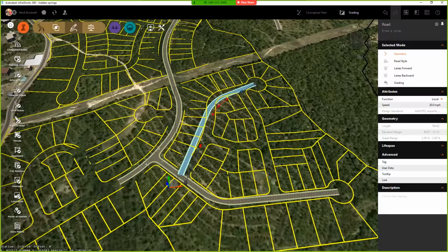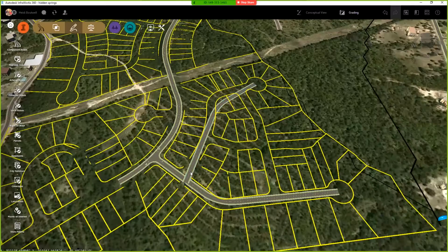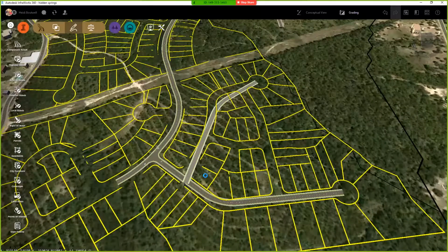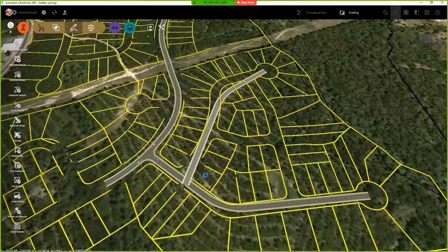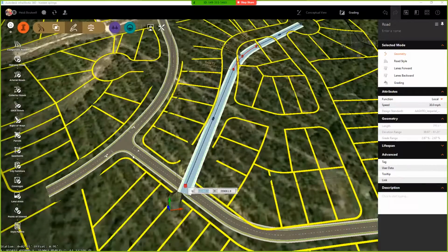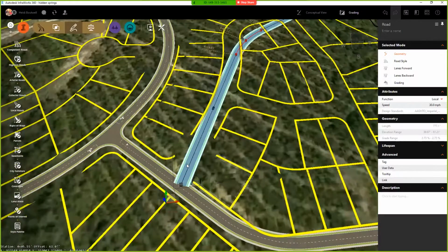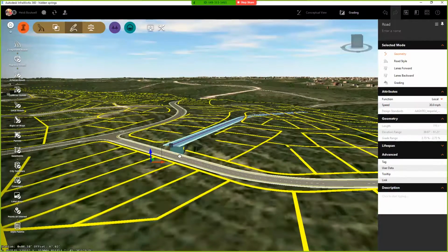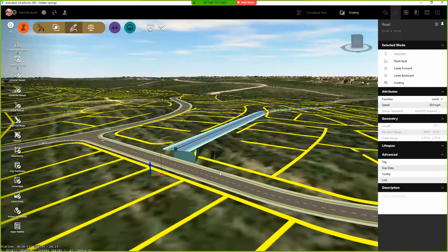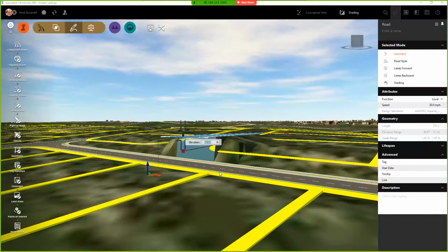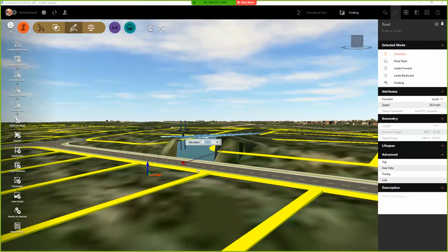Okay, I'm going to throw some grading down here somewhere. Once this gets done, escape once to get out of it. I love how it did that. Let's put that back on there. Intersection. We want a real intersection. We don't overlap. That's a real intersection. This happens because sometimes you get elevation. When it elevates, you just have to drag it down. So yes, you can modify the profile view and elevation. Look at that in 3D.